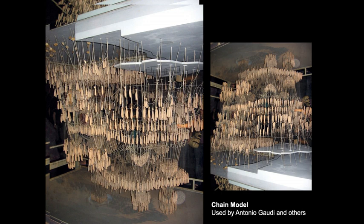And then you have to imagine that you fix this chain and turn it upside down, or you take a picture and flip it 180 degrees, so the bottom is on the top now. And so then you have the form for an arc, or you can also construct a dome like this. And you can also make an experiment: you link some other chains, and then you come to this model.